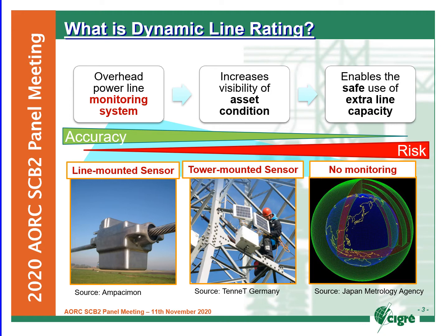As you can imagine, the most accurate way to observe the power line is the direct method. Without local observations, there's no way to validate the accuracy of a model, and even then, you have to downscale it to account for uncertainty. With the tower-mounted system, the accuracy improves compared to the computer models, but you still have local differences in weather conditions, especially wind speeds, between the tower location and the power line. This is reported by several Cigre papers already. The discrepancy is greater if you have complex terrain or obstacles like trees and buildings in the area, or you have very long spans. And this is why, if the asset is critical and safety is important, it's best to